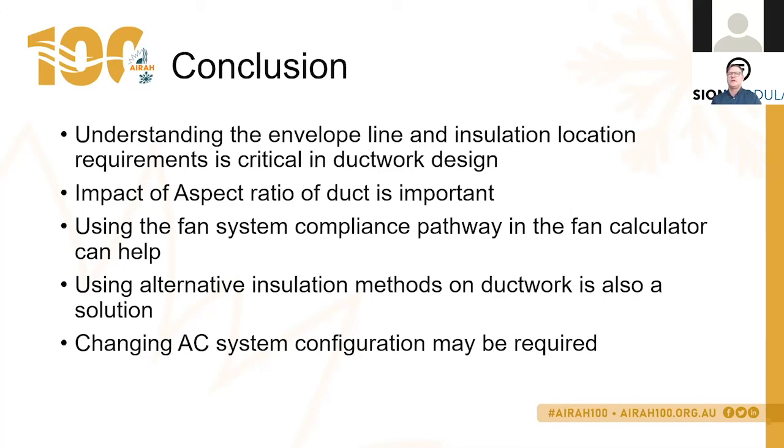Return air duct and exhaust duct don't have to be insulated as per Section J requirements, but if you're trying to achieve a certain efficiency on your heat exchanger or preconditioning setup, then you may want to insulate that ductwork. Difficult to answer without actually seeing a full design of the system.